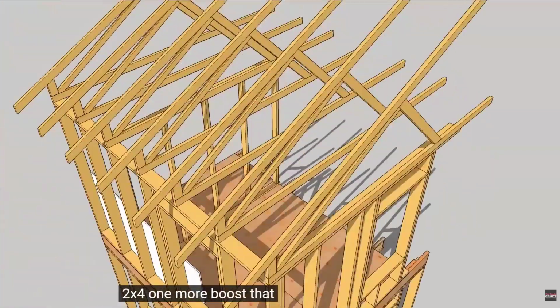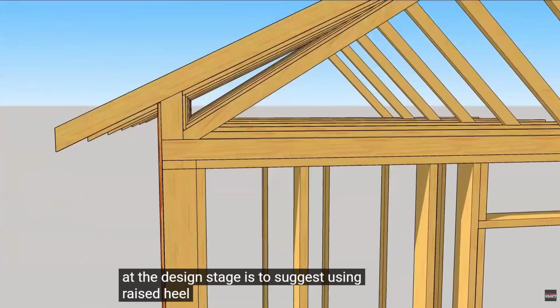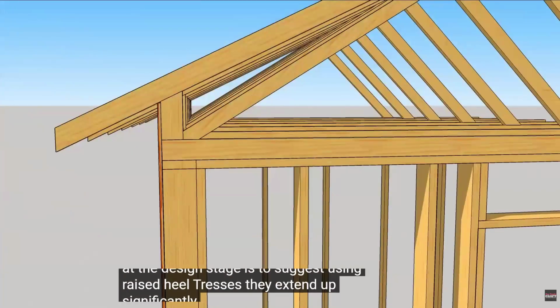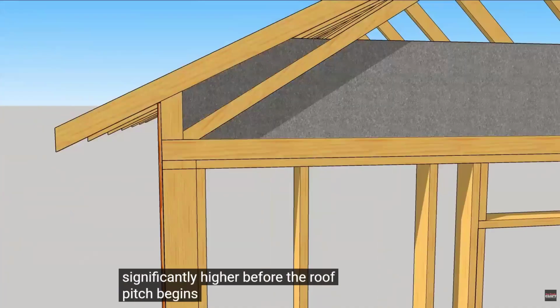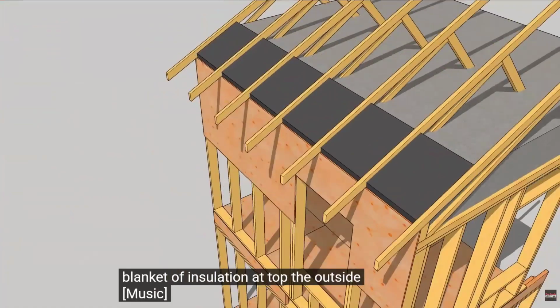One more boost that framers can add at the design stage is to suggest using raised heel trusses. They extend up significantly higher before the roof pitch begins, which allows a thick blanket of insulation atop the outside walls.